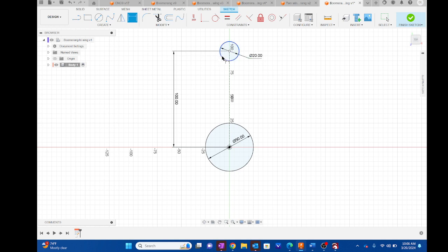And we want to create another cam shape here. So we have to go 50 minus 20 is 30 again. So I'm going to come in here and go X, so I get my construction line, type in 30 like that. And get my line tool, center point of this circle through to the tangent shape here, tangent constraint there, sorry.